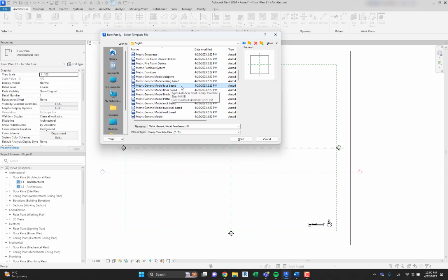it is quite often usable, phase-based as well as line-based elements. Those two are pretty common for you to use in Revit. And if you're a structural engineer, most of the time you're also gonna use the structural framing templates here, beams and braces, and so on. There's a bit of a difference between structural framing, beams and braces, and line-based elements, but we'll cover that in future videos. Now let's go with the model phase-based elements.